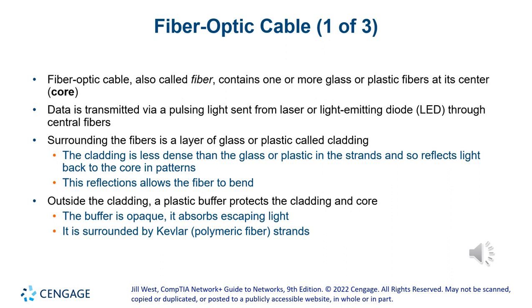Some people tend to look right at those things. It's a little red glow that you'll see on those lasers. Please stay away from that. There's a warning on those things that it might cause damage to your eyes, so don't look at it. I've seen engineers actually looking at it, going, oh, look, there's a light, there's a signal. Please don't. There's equipment made for that, that you can use to see if you're actually seeing a light or no light.